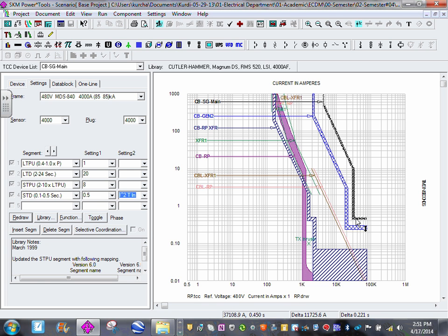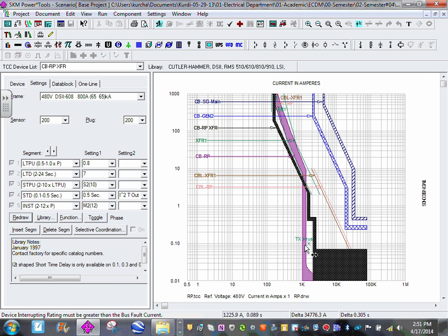So anyway, you always keep in mind that right now, especially with the 70E and with reducing the arc flash, you'll always be better. I want to emphasize that one. I don't know if you guys can see that little inrush for the transformer. For example, if I move this one in here, that's feeding the receptacle panel, now every time you start your motor, or when your transformer is energized, it will trip because you have to clear. So what we do is we shift it up, but the further to the right you shift it, the less safe your equipment would be. So we try to adjust, and there are IEEE standards for how far you can go and what's not.